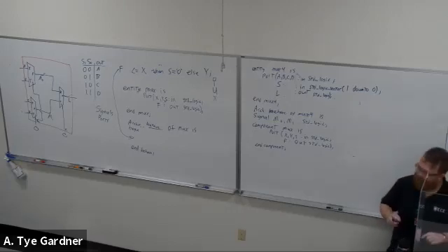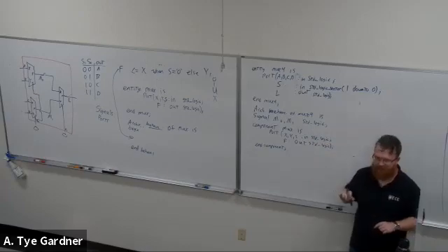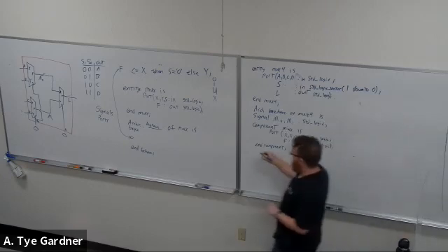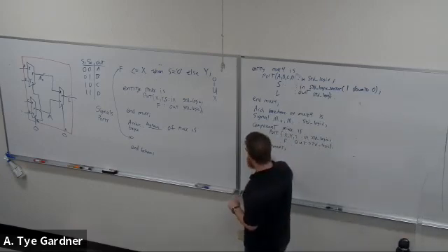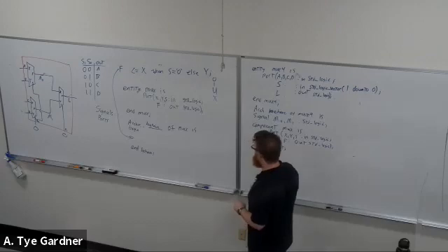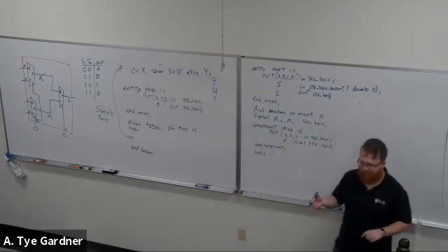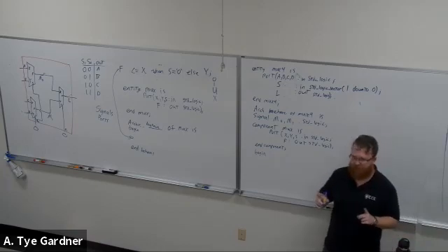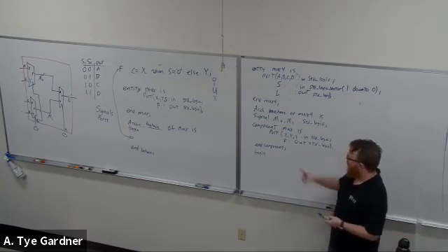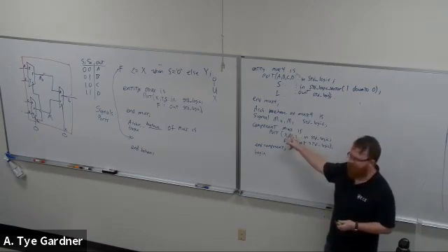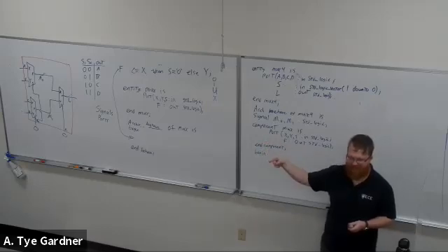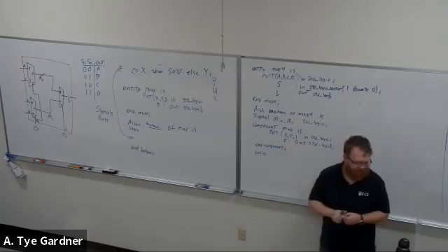Okay, now I have signals that exist. I have components that exist. Yay, right? Okay. Now I can do the begin of my architecture. And I need to tell it how they are connected. Now, the thing you need to resist is rewriting the mux code, right? There is no reason that I need to program 3 muxes, because it's the same thing. So I'm just going to tell it the mux exists 3 times. Okay.